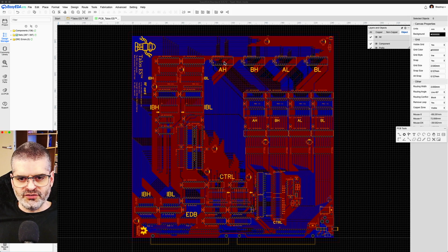So the registers can latch the value of the local bus because the local bus wraps around until the top of the register chips. So you can load a value into the register from the local bus lines here on top. And from the same lines, you can drive LEDs to show what is on the local bus, not what is on the registers. These LED bars here show what's on the registers. These bars show what's on the bus itself.